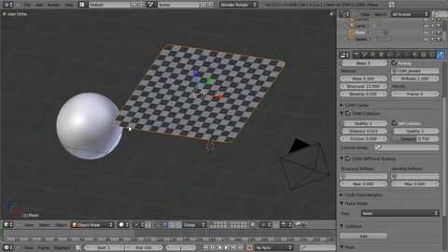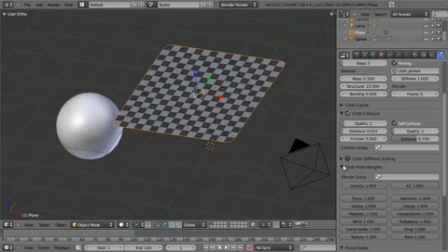Say maybe we want the top bar here to be much more structural, then just assign a weight of, say, 0.75 or 1. Same thing with the bending. And so that allows you to further add some variety to the cloth and get more control. We're not going to worry about that for the time being. Same thing with cloth field weights.